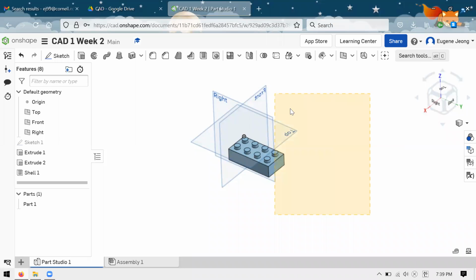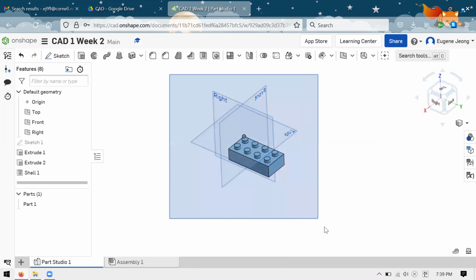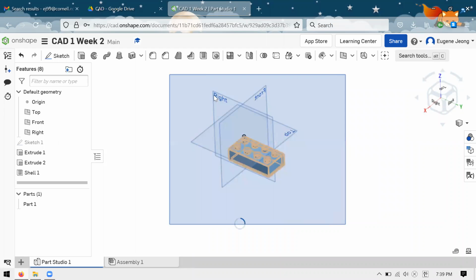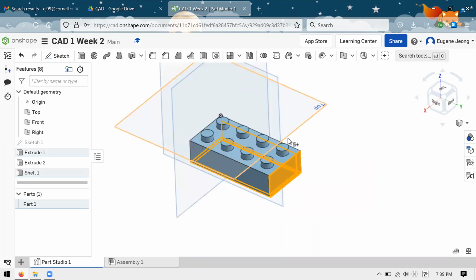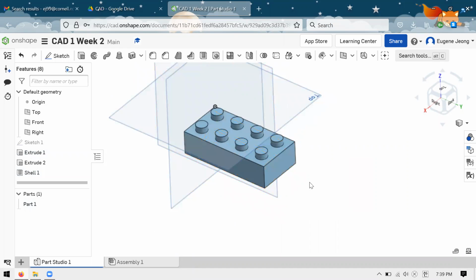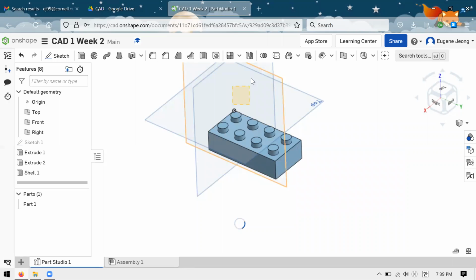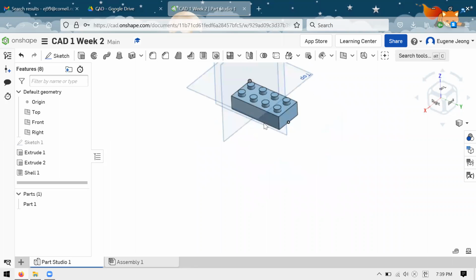They're actually different, and you can see this way it creates a different colored box in this way. So this is your standard: you have to encompass the whole thing to select it. And if you drag up and to the left, you only have to select a part of it to select everything that's even slightly intersecting with that box. So this one is more inclusive. You can select everything just by touching it. And with this, if I just touch things but don't encompass them entirely, it doesn't select anything. Whereas if I did this, it would select everything. So that's the difference between those.